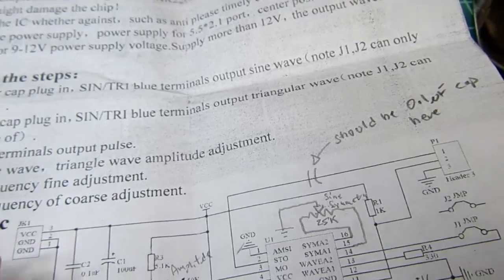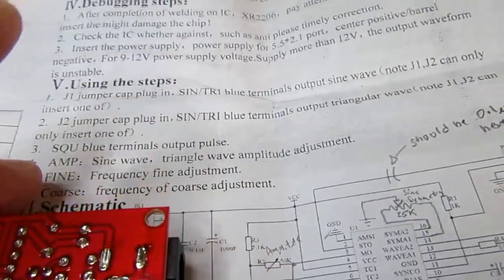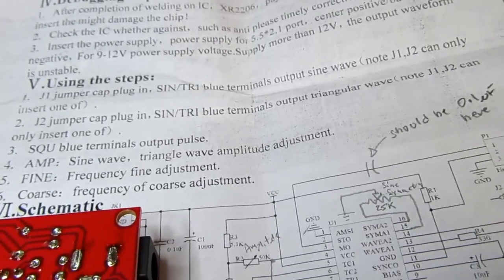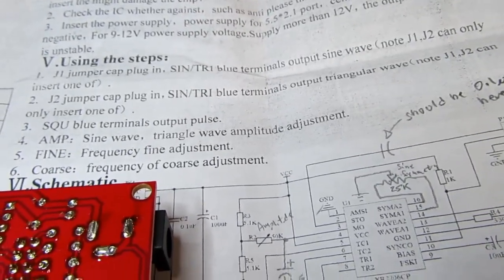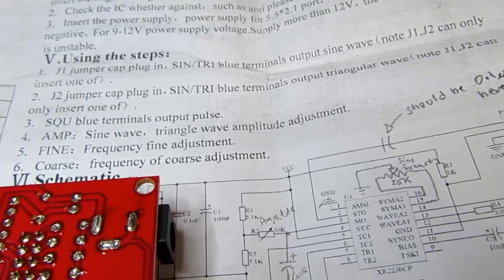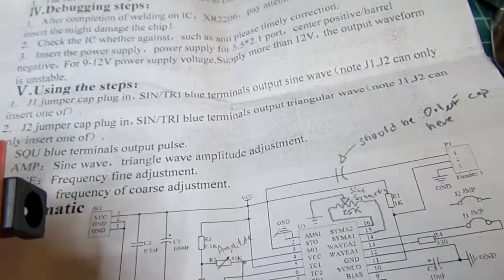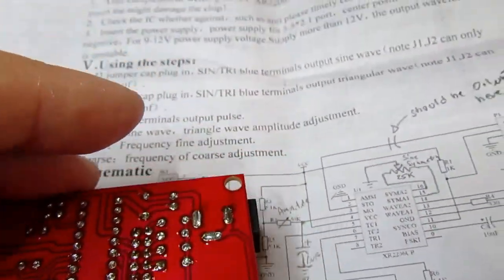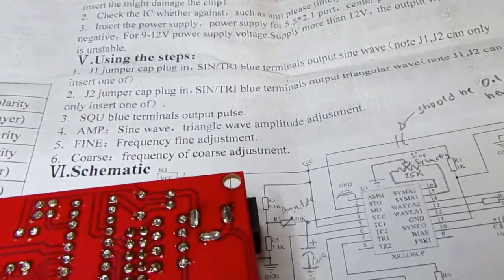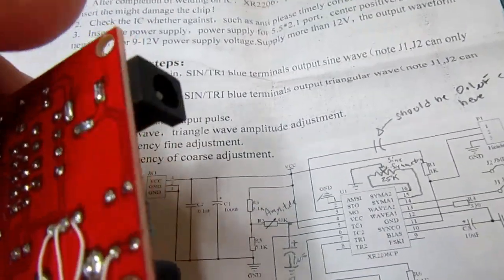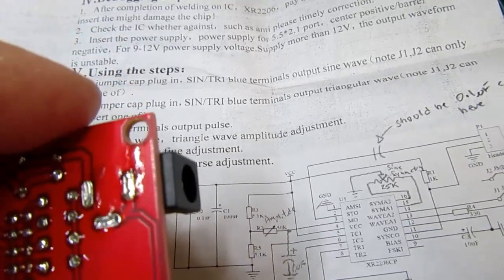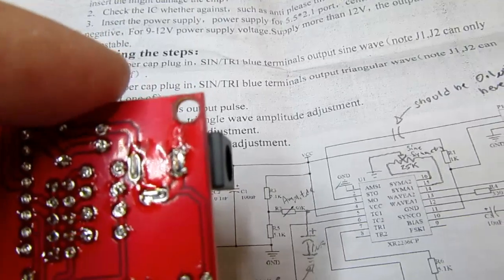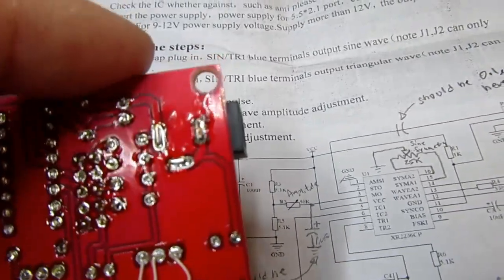Now, if you had this running off of a bipolar power supply, then the output would be centered around ground, and you wouldn't have to worry about that. But with a unipolar supply, it's going to float somewhere around 4.5 volts if you're using a 9-volt supply. And again, I'm using float incorrectly. It's going to be offset from ground by about half of your power supply voltage, which is something you don't want.